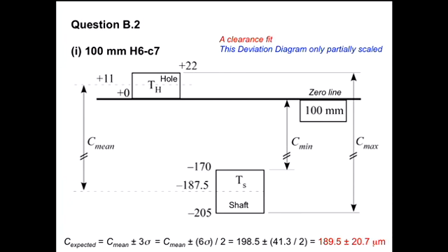That's good I've done this and told you about it. The boxes are scaled within themselves. But these clearance arrows, or distances, have got those little dashy lines across them to indicate that to do it in a fully scaled way loses the opportunity to be able to put the tolerance diagram into a reasonable state. That would be perfectly acceptable if I saw you do that. You demonstrate you understand what you're doing. And the expected clearance goes through all this.